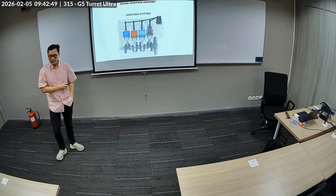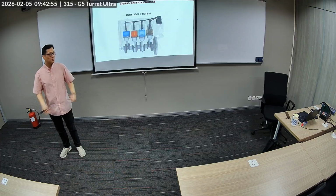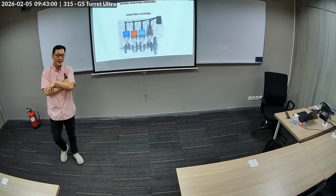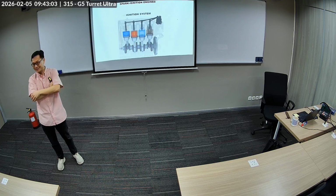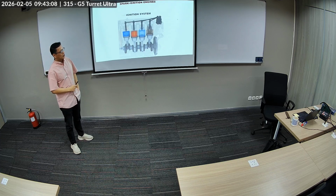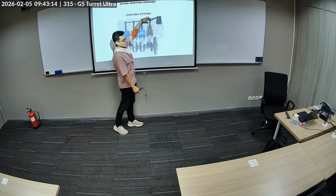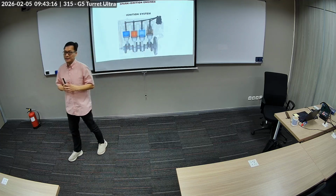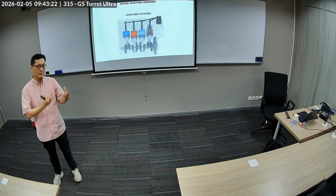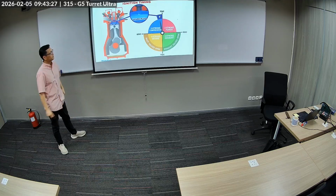It used to be that when you had heavy rain and flooding, you would splash into the distributor. That's usually the first place you go to if your car breaks down during a heavy rain or some flooding. But nowadays, this is all electronic. The coil is often here. It's also called a coil on plug system. The coil's job is to increase the voltage, like from 12 volts all the way up to like 20,000 volts, to create the spark at the spark plugs.